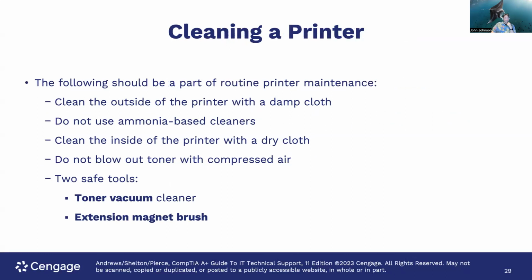And for cleaning a printer, the following should be a part of your routine printer maintenance. Cleaning the outside of the printer with a damp cloth, that's just nice and general. It also keeps dust and any toner at bay. Do not use ammonia-based cleaners for this. You can also clean the inside of the printer with a dry cloth. Don't blow out toner with compressed air. That's a very bad idea. You'll want to use a toner vacuum for something like that, or you can use an extension magnet brush.